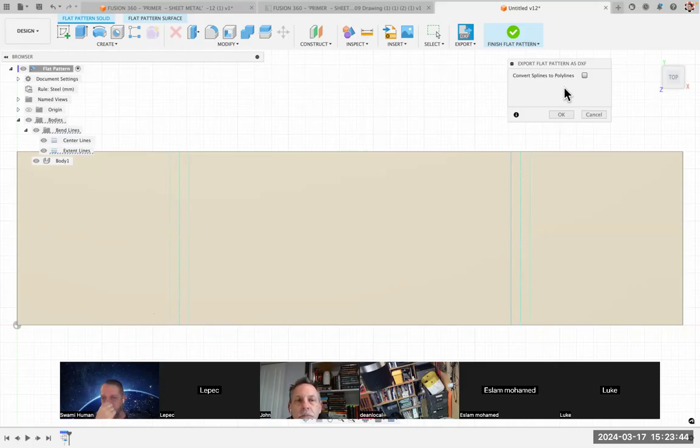Some older controllers and firmware and such are not happy with these fancy splines. So if you have to, you can convert them into many straight lines approximating the curve. So you segment or linearize the curve into polylines, many lines. So you just have to know your machine or the service you're using, whether this is important or not.